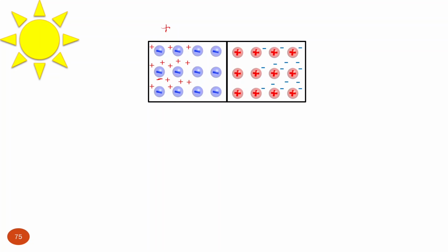So in total, some net charge is positive at this edge of the p-n junction. In a previously neutral region, now it's not neutral anymore because we have more holes than negatively charged acceptors. And the same, we have some excessive, net negative charge in the n-type region.